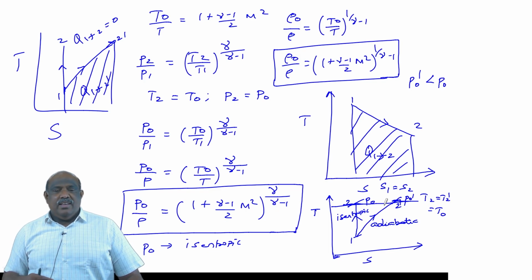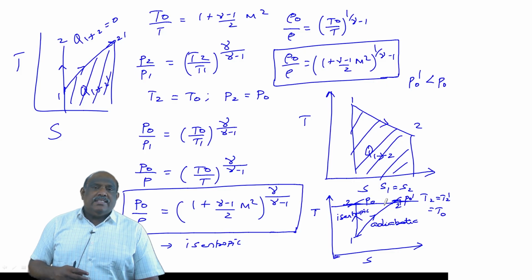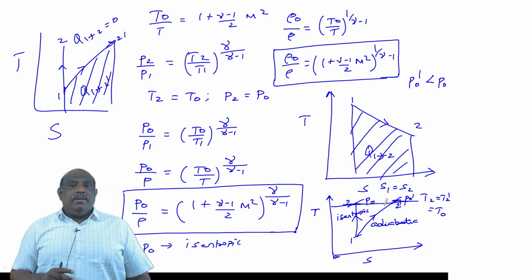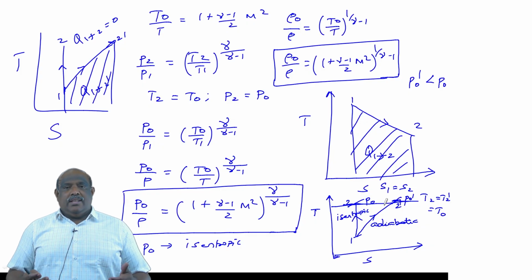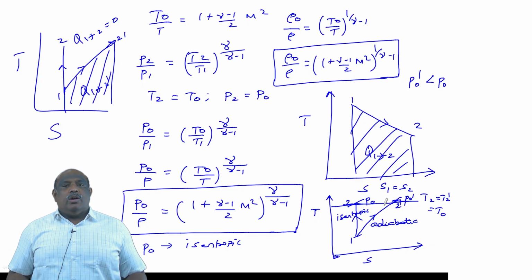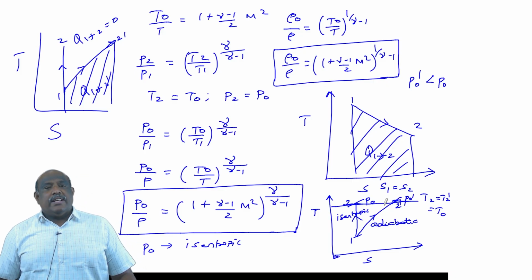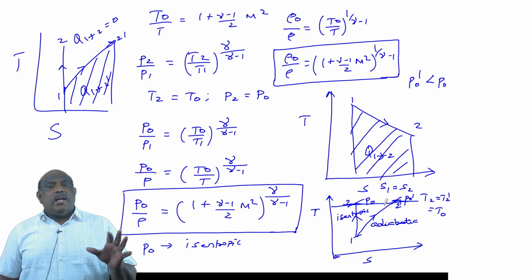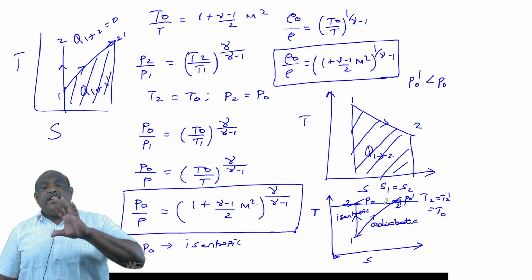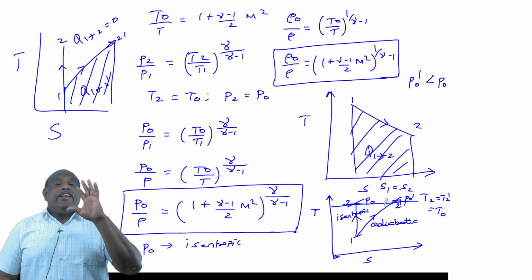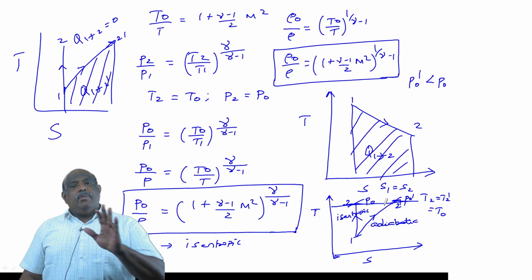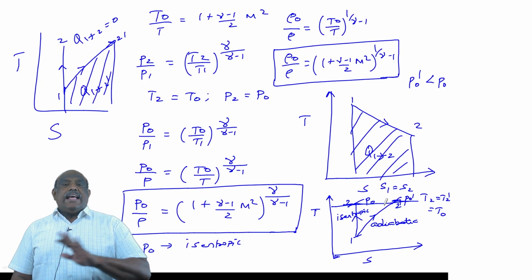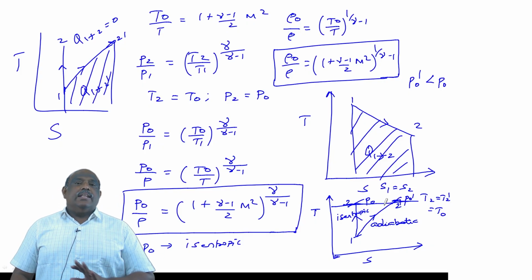Yes, you are right. The reason is that it is not reversible, it is irreversible. Because of irreversibility, there are some losses. That losses which will be equal to the heat transfer is shown in the graph as what? The area under the graph 1 to 2 dash. So, the area under the graph 1 to 2 dash is not due to adiabatic nature, it is because of the irreversibilities. If we are able to understand this much, then gas dynamics or thermodynamics is nothing.